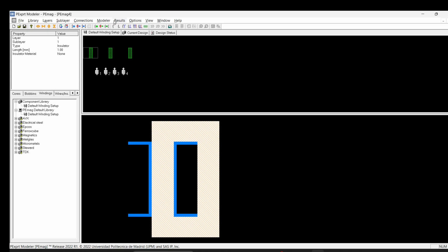You can convert it using this clockwise monofilar option. So it will create one winding. And similarly for this third one, we'll do the same. Based on how you are winding it, you can select either clockwise or counterclockwise. In my design, both are clockwise, so I'm keeping it like this.